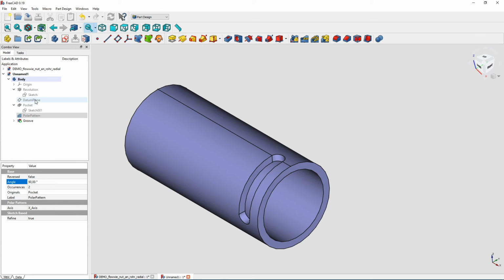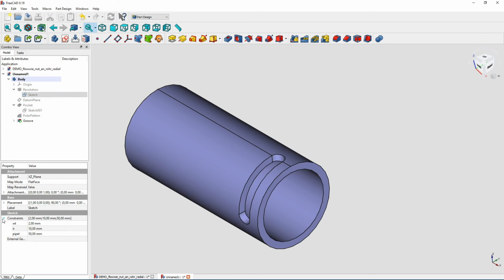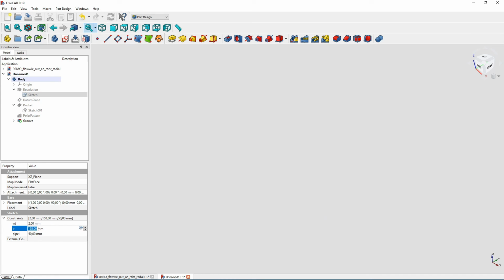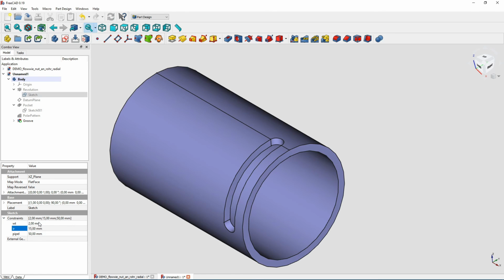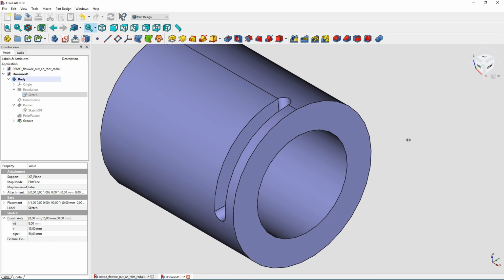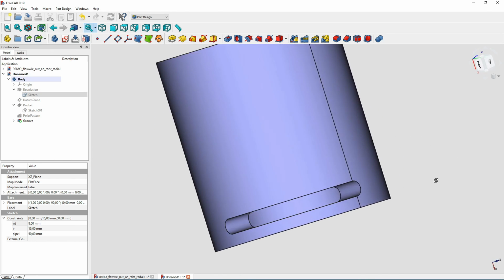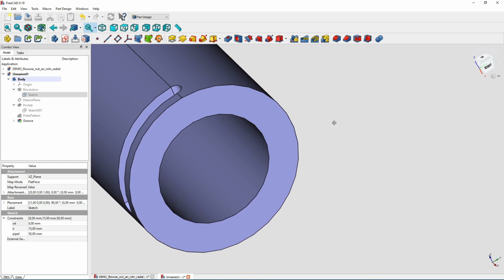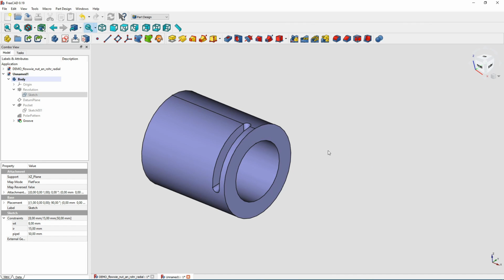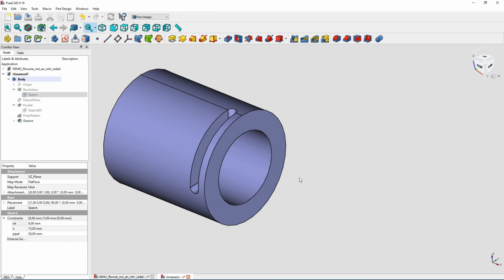And whatever I change now, let's say the diameter of, or the inner radius. Oh, 158 was maybe a little bit too big. Pipe L and wall thickness, maybe make it a really thick wall, 8 millimeters, but still my slotted hole will go through the whole pipe. Okay, that's what I wanted to achieve.